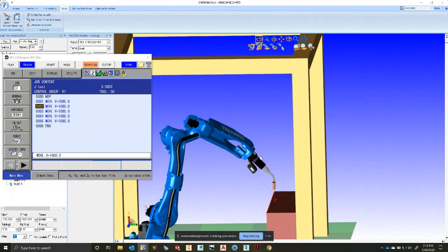The simulated robots don't have torque sensors inside them. Even then, it has to detect an object, so it has collision detection. If you want to simulate collaborative, you can simply turn down the speed of the robot, and then it'll slow itself down that way.